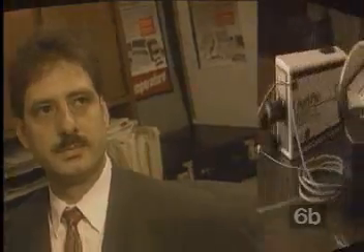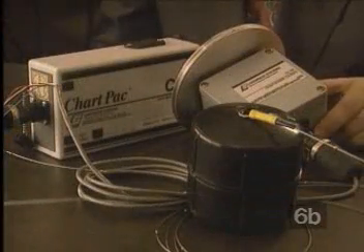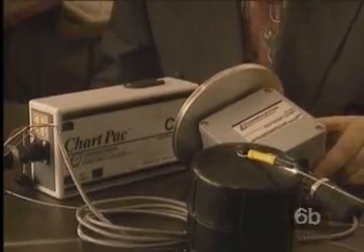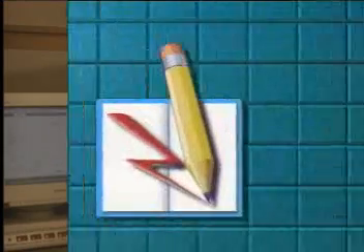Once we've got the coefficients, the customer can then take the water level recorder back out into the field with the data logger and record the voltages, and then bring the data logger back in and download the voltages into the computer and have it calculate the water level in meters using the fifth-order polynomial, as long as the water level stays within the domain of the data we gathered to generate the coefficients.